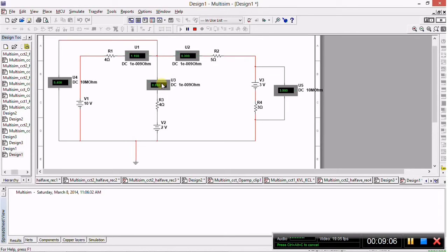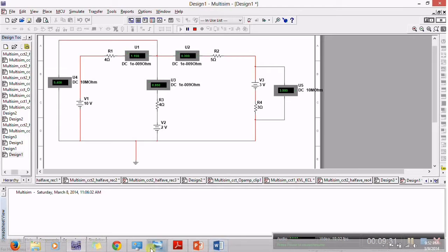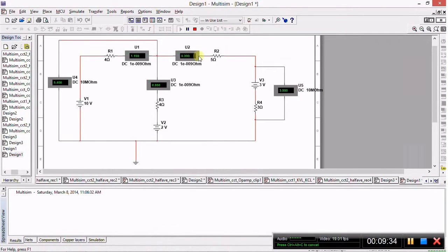law. Kirchhoff's current law states that the sum of the currents entering a node is equal to the sum of the currents leaving. So, for instance, the diagram denoted I3 as leaving this node. So, I3 is 0.85 amps. Therefore, one of these currents on top must be negative to be summed and give you the answer as 0.85. Therefore, this current I2 here is actually negative 0.3 amps. Therefore, 1.15 plus negative 0.3 gives you 0.85. And there we have demonstrated Kirchhoff's current law.